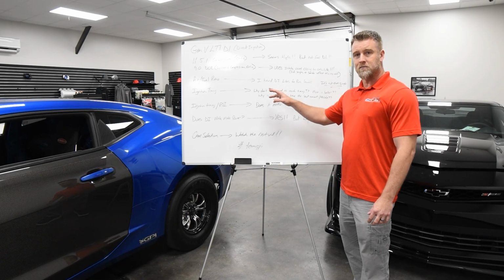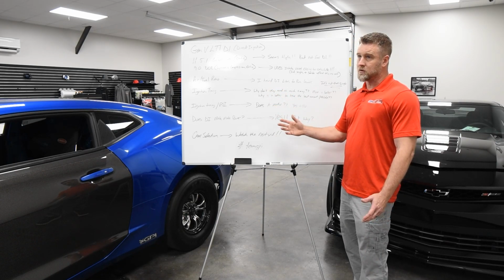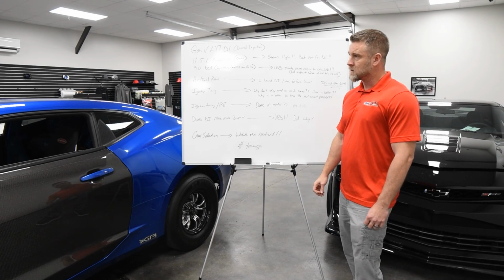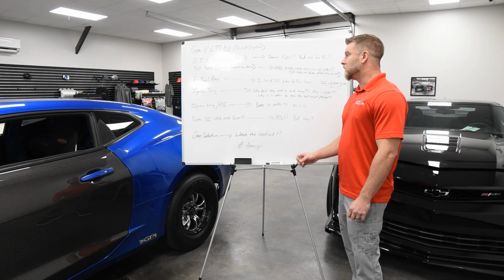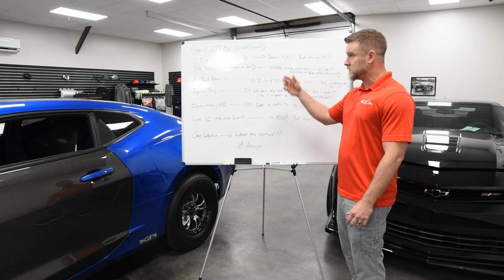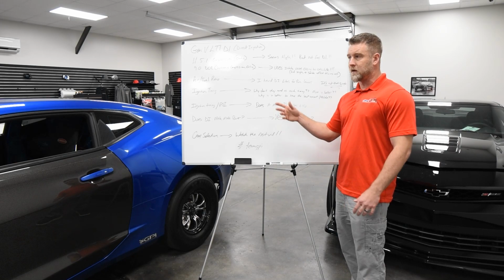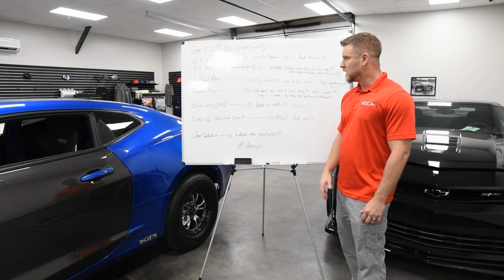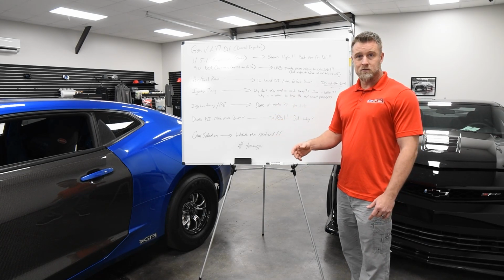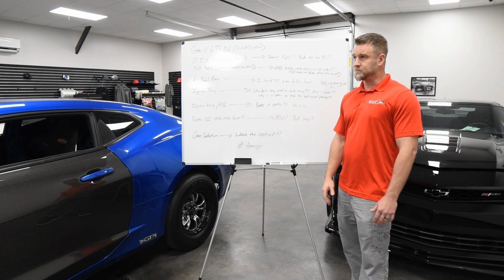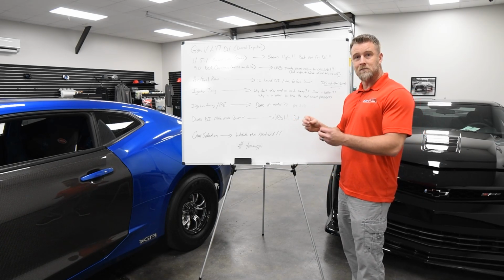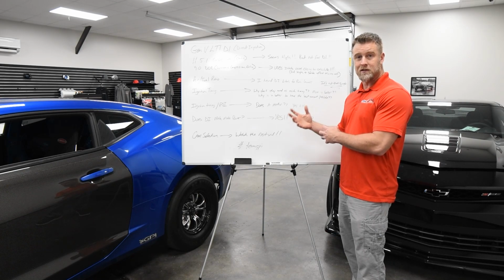Same thing when the guys are boosted. You can run that thing a little bit leaner, but it doesn't always have to be leaner. I'll give you a perfect example. Let's say you have an LT4 or an LT1 that you've built this setup and it's boosted. Let's say like 90% of the guys, you have to put methanol injection on it. Maybe you haven't gone port injection. When you start putting methanol in there, it starts acting more like a port-injected engine.